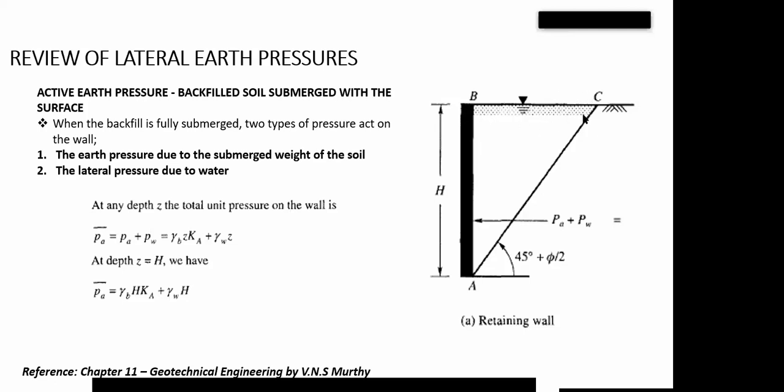That denotes that our pressure keeps on increasing, and I explained earlier why. It is because the increase in your active earth pressure, or the pressure due to water, is dependent on your height. So the deeper your retaining wall, the higher the pressure.